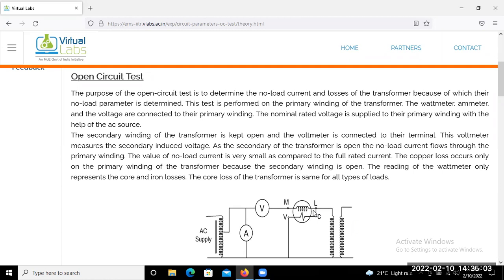The next point is to move this variac. This is your moving point of the single phase auto transformer. So whenever you move this point, you may see the reflection in the voltmeter reading where you connect the voltmeter here. You observe that this voltmeter indicates the rated voltage of this LV coil.